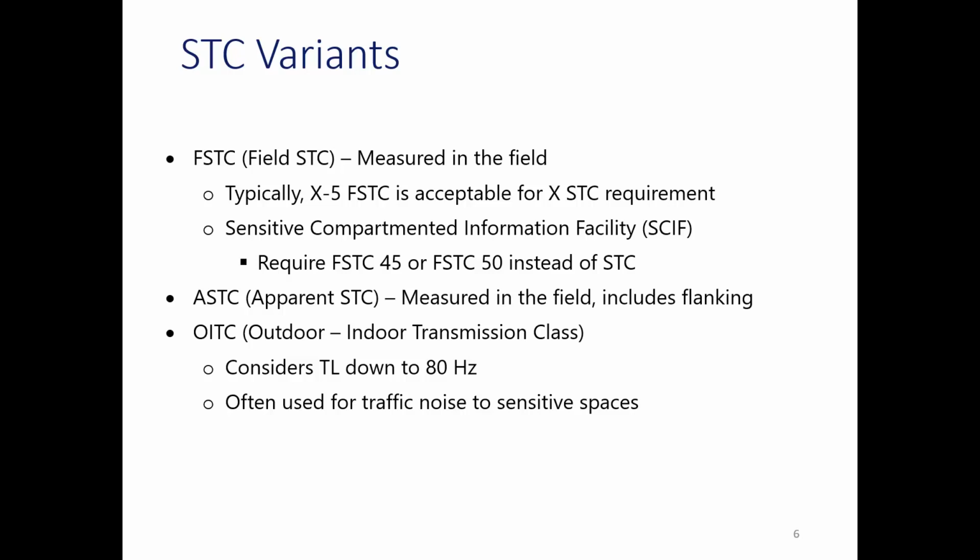But at the top, they just had a lightweight metal roof that spanned over both sides. And they fired up one side, and you could hear it clear as day on the other side. And they're wondering, well, why did we get this? We put an STC 75 wall in between here. It was because of flanking.